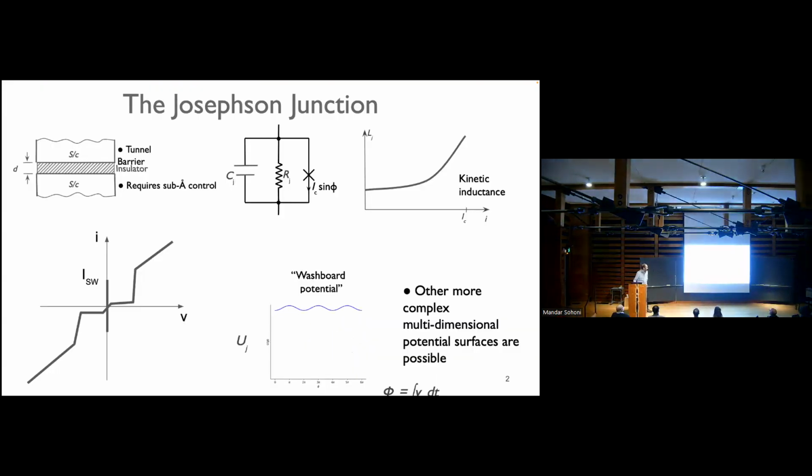So first of all, I'm going to start with the Josephson junction. The Josephson junction is the core technology of the qubits. They're the core technology of, if you've heard of it, SFQ electronics, which is the superconducting classical electronics family. They're the core technology of the SQUID, which is the best magnetic field sensor out there. And they're basically the start of all superconducting devices.